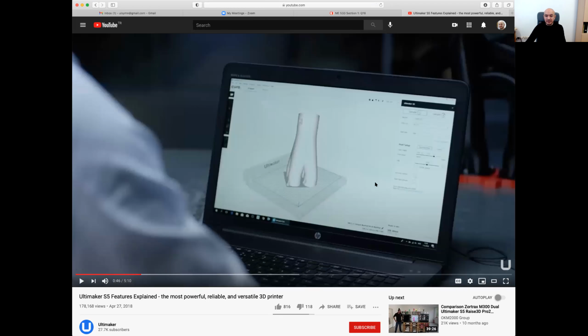So this is a kind of software they are using for printing. They start with the STL format of the design, and then here in this CAM software, complete manufacturing software, they actually take slices of this part, and then generate the paths for the deposition of material.